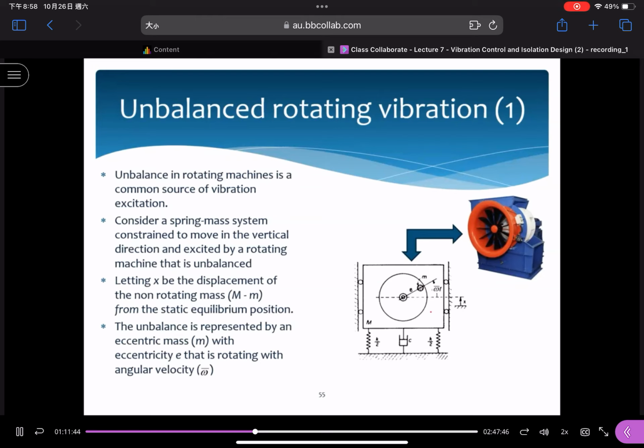The rotating mass we can regard as a small letter m. What is e here? We call this the eccentricity. You may regard this as the length from the center to this mass. Any problem? And the rotational speed is relevant to omega bar times t. In this slide I just picked up some important points. We consider that s is the displacement. When this mass is in rotation, it creates vertical motions, up and down. Because of the rotation of this small mass, it creates an unbalanced force.